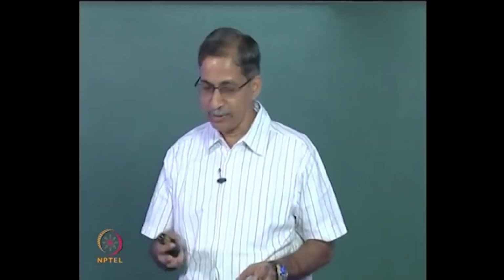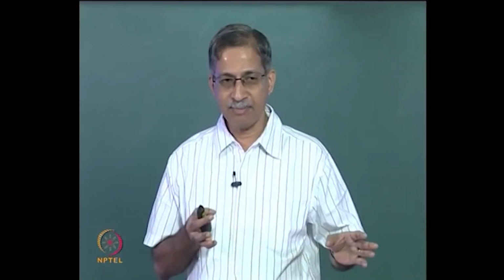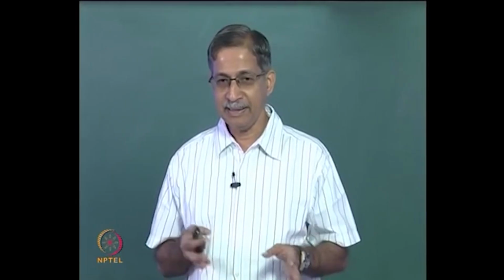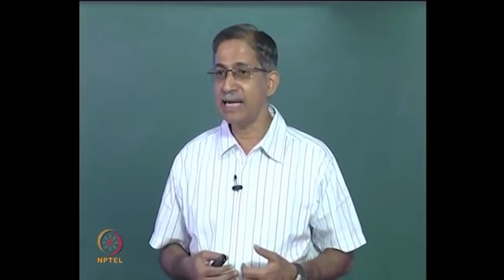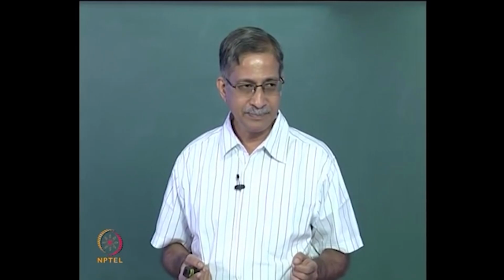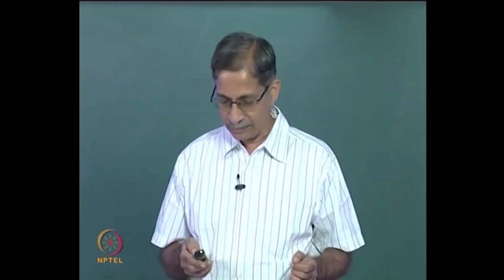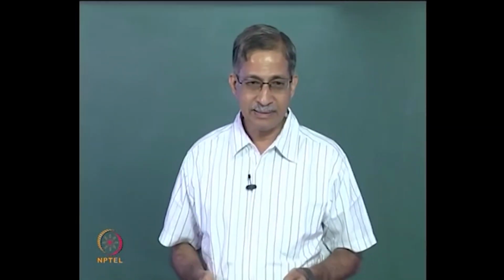First, with regard to the type of indeterminacy. Static indeterminacy, which means you are talking about unknown elements in the force field, so that is part of the force methods. And in displacement methods, we worry about kinematic indeterminacy. Okay, that is one major difference. What else? Okay, so first the type of indeterminacy, which you have answered.